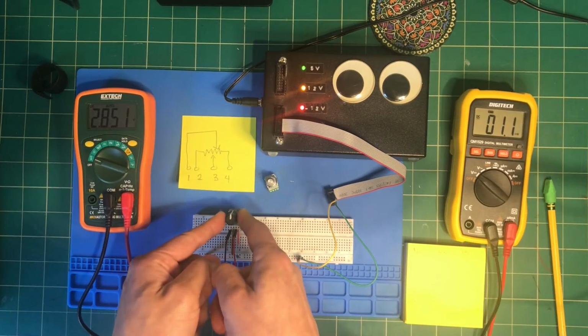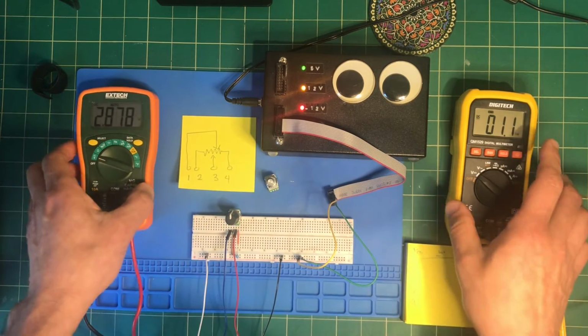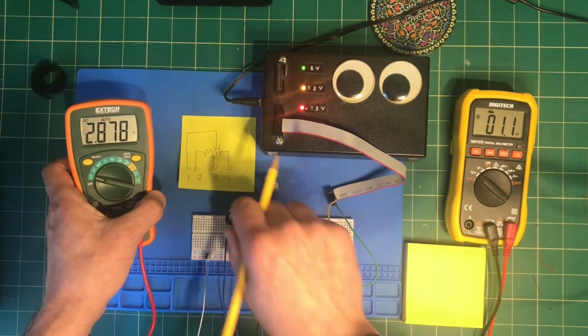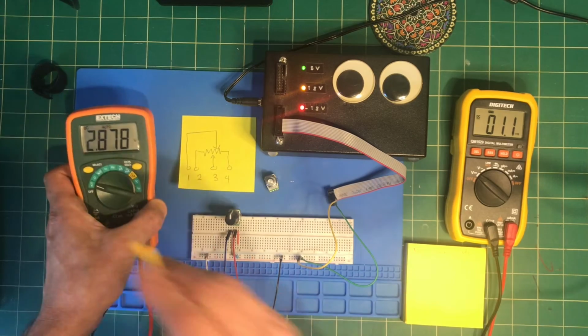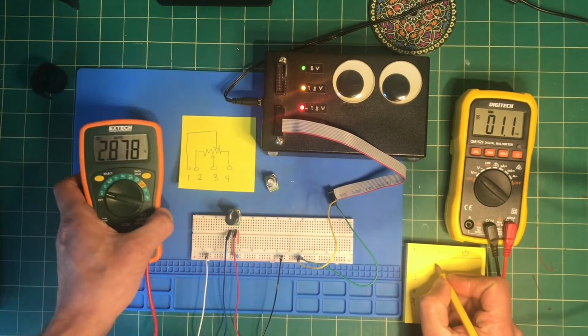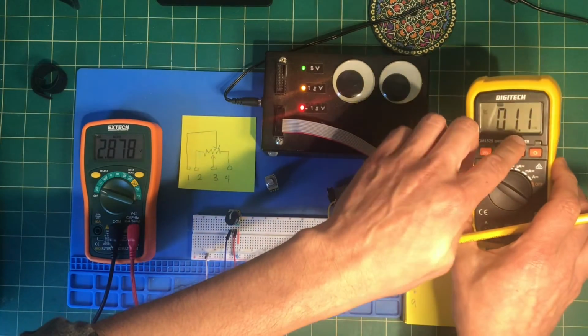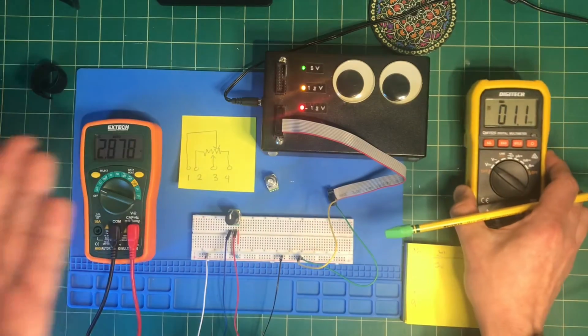Okay, so right off the bat, we can see this is at the 12 o'clock position. And sure enough, this is really close to 3 volts. In fact, because it's going to be really difficult for me to get an exact reading in there, we're going to assume that that is 3 volts for the one on the left. I'm just going to write it down here. And this one here is like 1.1 millivolts. So essentially this one here is 0 volts.